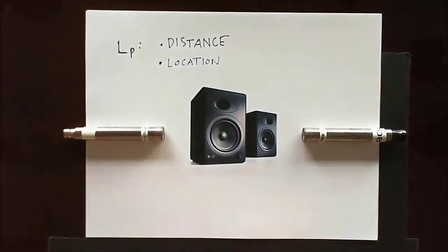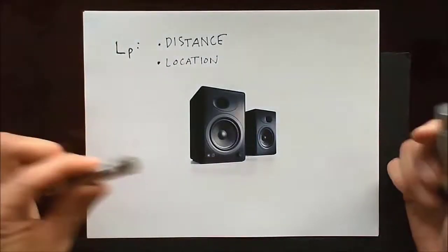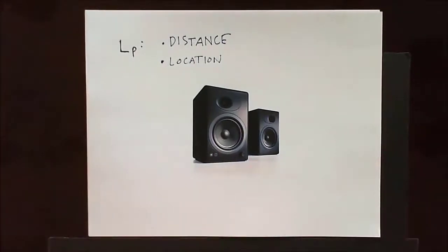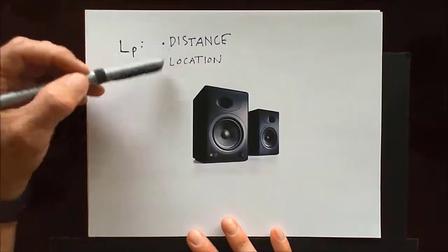Okay? So while I can use sound pressure to say how loud this device is, I also have to keep track of exactly where I'm measuring and how far away I'm measuring from that object. So that can make it very difficult to compare measurements across different facilities or measurements made by different people, because you have to specify all of these things precisely. And the truth of the matter is not everyone has access to the same acoustic environment or laboratory conditions perhaps, and so we have to be able to make these how-loud-is-this-object test campaigns without so much reliance on knowing exact distance and location.